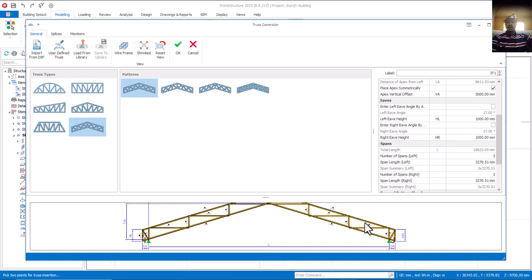You know, this is your rafter. Is that okay? This one is double, top chord and bottom chord, isn't it? But in terms of your rafter, understand? So you have your purlin on top of rafter. So the distance between one purlin to another, center to center, we are talking about 3270.51 millimeter, which is quite much. So I need to reduce it. Is that okay? So something like maybe 1000 or 1000 plus or 900.